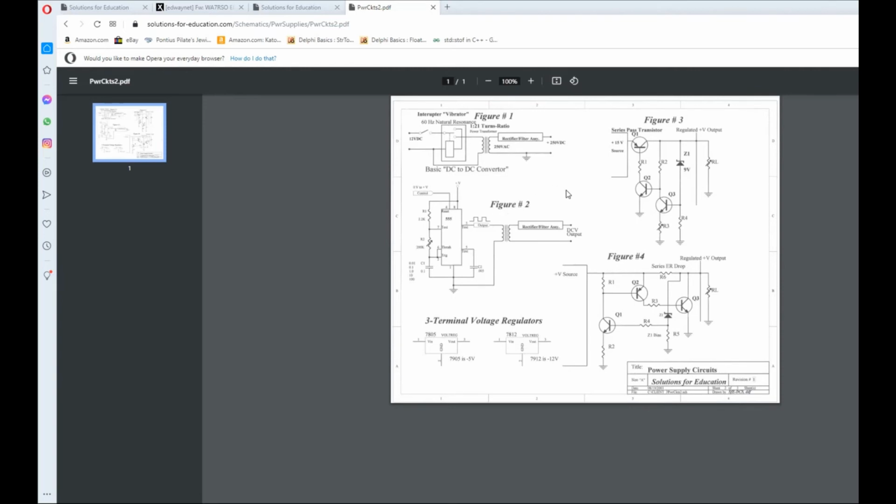Okay, if you want to do lab work, and some of you would like to play around in labs, and some of you could care less, but let's do this. Here is a very favorite chip for a lot of experiments, called a 555. The 555 could be run monostable, but it's typically astable, which means that when you turn it on, it has a square wave output. You can vary the frequency of this through the primary of this transformer, and because it's pulsating, it acts like AC, and over on this side you'll have, guess what? AC.